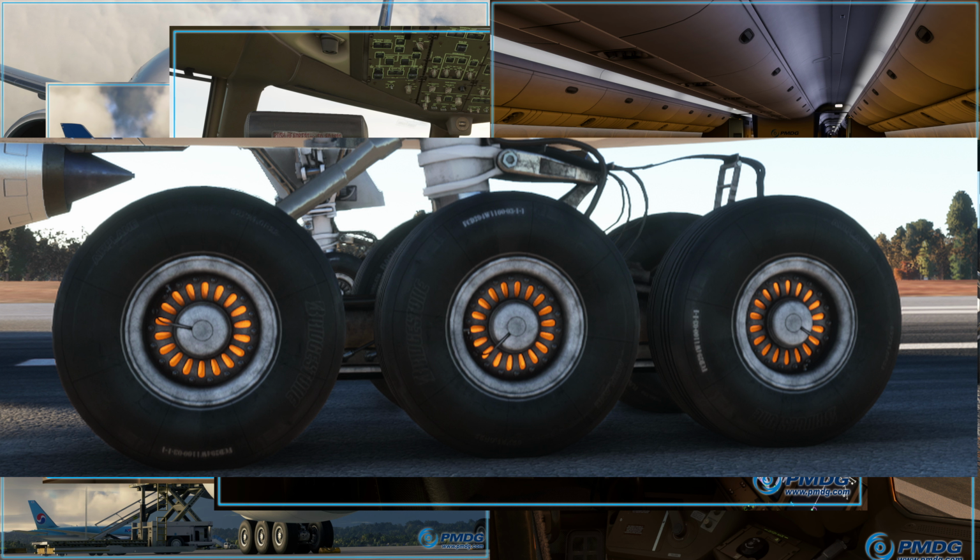That is going to cause the fuse plugs to melt inside the tires, and that is ultimately going to cause the tires to fail. But in normal circumstances, you shouldn't expect your tires just to blow up. There are protections built into that, so-called fuse plugs, and they are going to melt before the rest of the tire starts melting. For that reason, unless there is any damage to the tires, the brakes or the tires are going to just normally deflate without just blowing up.